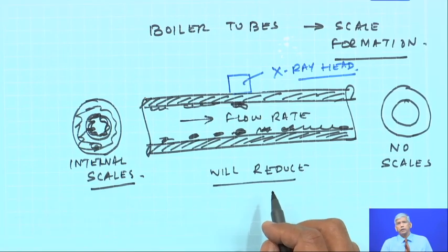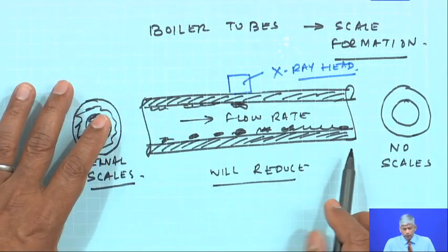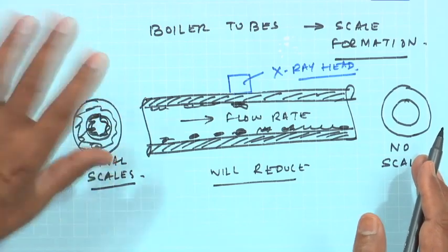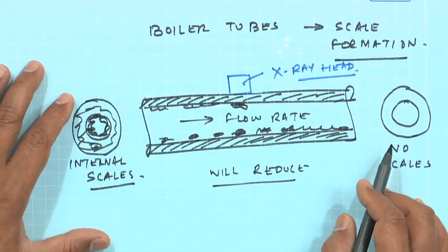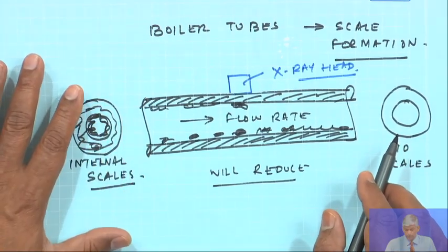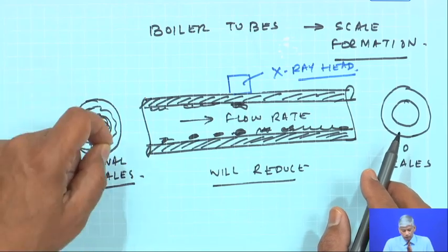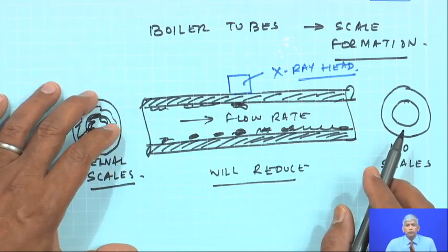So, periodically you can do, because see, let me tell you, in such a steam power plant, the boiler tubes would not vibrate, okay, other than a flow induced vibration because of turbulence, etc. That is a different story altogether, and the vibration is very insignificant. On top of it, it is definitely not convenient or not desirable to measure the vibrations in a boiler tube when the boiler is in operation.